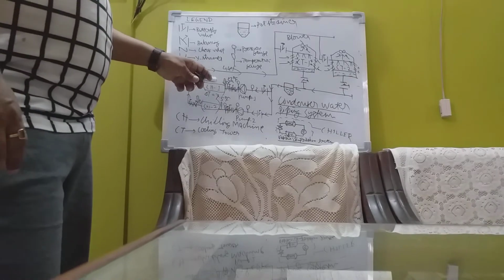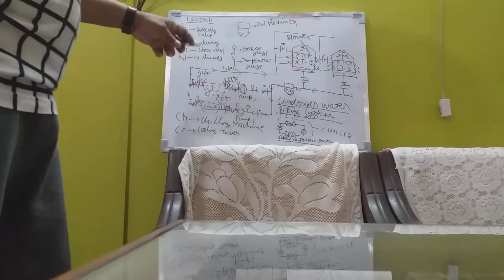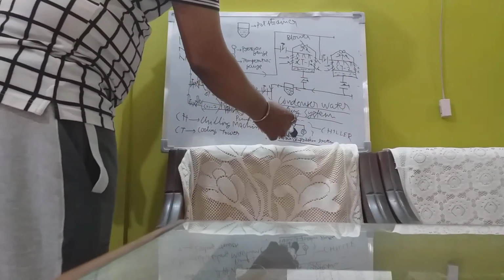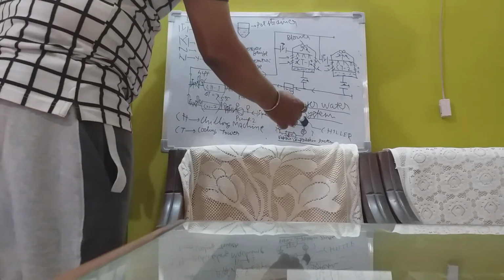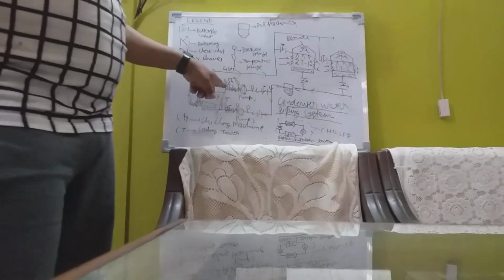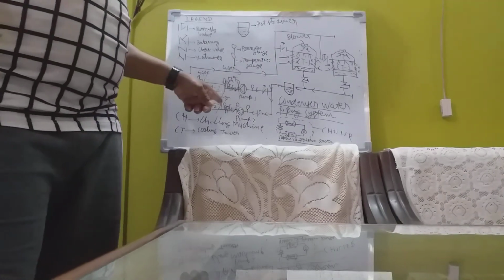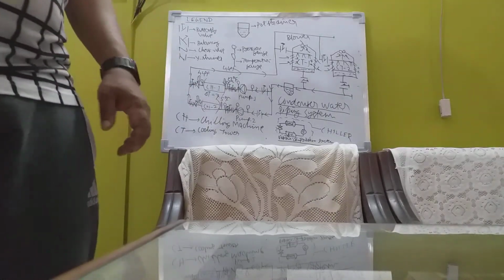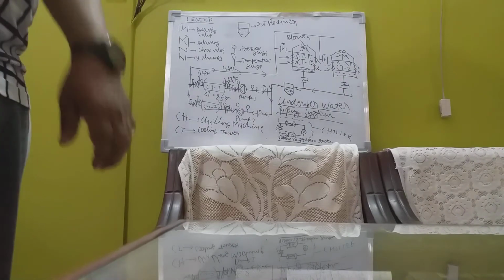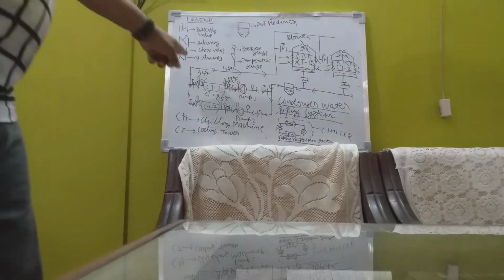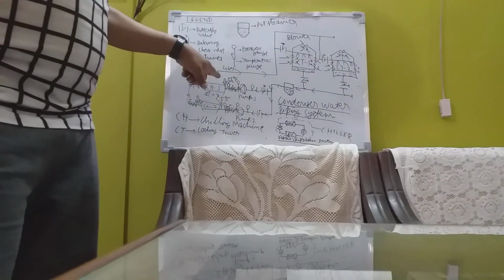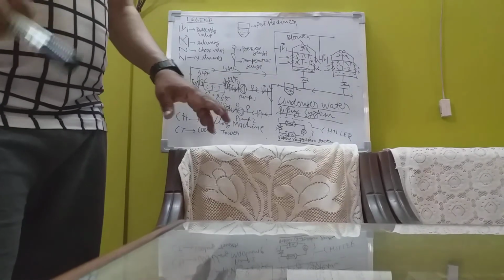In case of condenser, the water gets heated up, taking heat from the condenser. What is happening? This refrigerant which comes in the evaporator then goes to the compressor, the temperature increases, it comes to the condenser, and it rejects heat to the condenser. So it rejects heat to the water. So in case of chiller, the water gets cooled. In case of condenser, the water gets heated, because we are cooling the refrigerant of the condenser with the help of water from outside. Now that hot water is to be cooled again, because we have to supply cold water to the condenser to cool it.